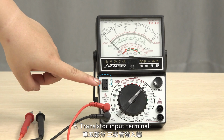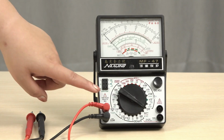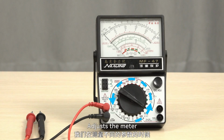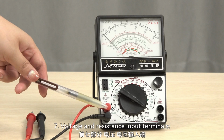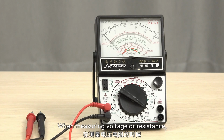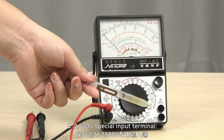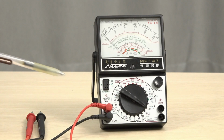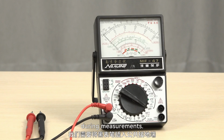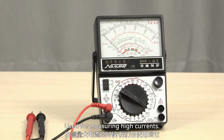5. Transistor input terminal. This is used to measure the amplification factor of transistors. 6. Range switch. Adjusts the meter for different measurement ranges. 7. Voltage and resistance input terminals. When measuring voltage or resistance, we insert the red probe into these input terminals. 8. 2500 volt special input terminal, used for high voltage measurements. 9. Common ground terminal, where the black probe is inserted during measurements. 10. 5 amperes current input terminal, used for measuring high currents.